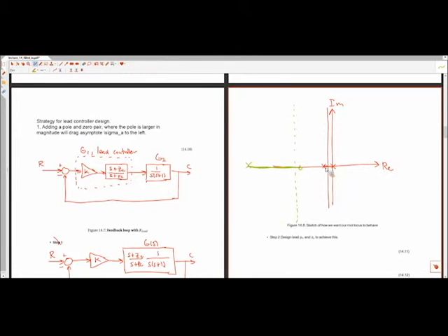When the portion of root locus here breaks away from the real axis, instead of going along this asymptote here with this intersection, it's now going to go along an asymptote moved farther to the left. So by adding this pole and zero, I have distorted the root locus plot in a way that's favorable for us in terms of creating a controller. Any questions about that idea?